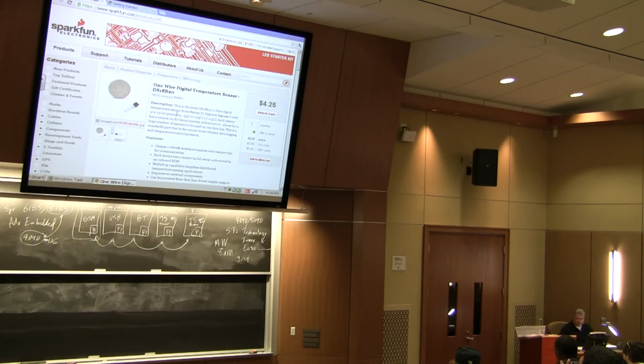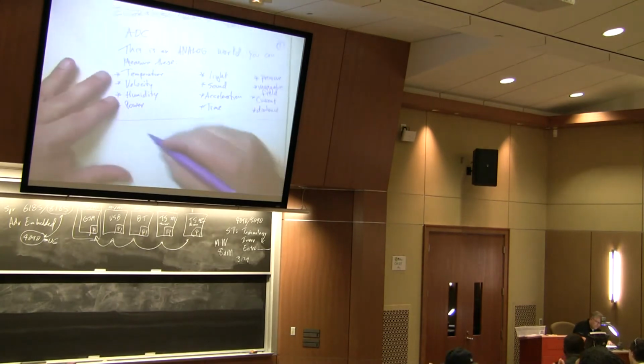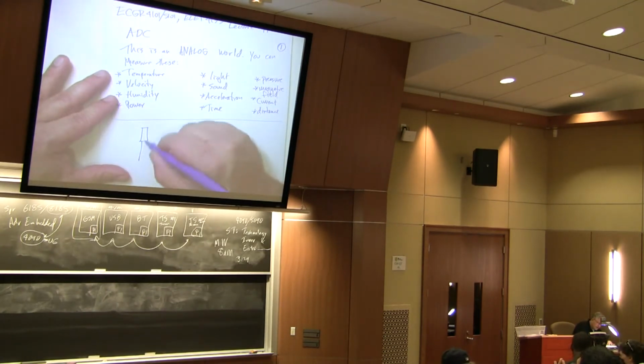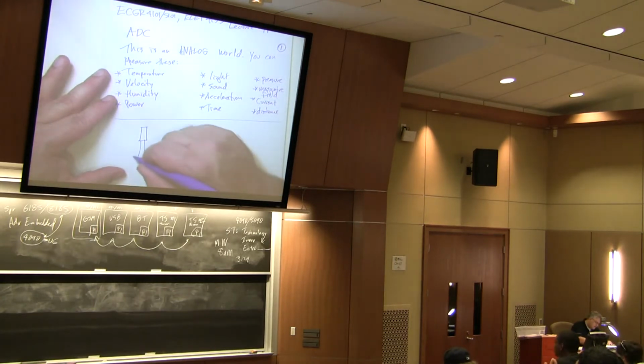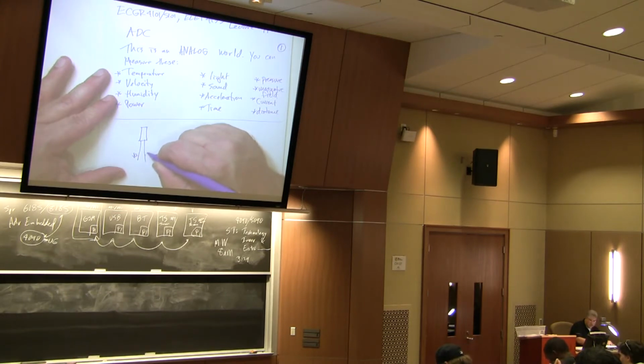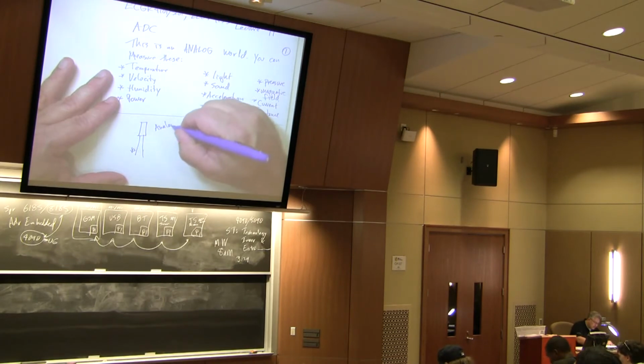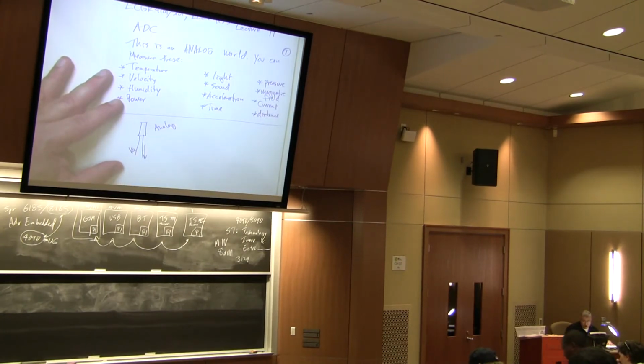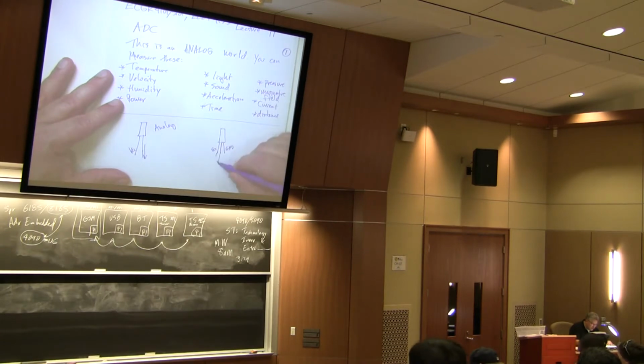We have an interesting situation with this. I can do one of two things. I could provide a device here that uses analog. So in other words, you give it a voltage, VCC, and then you measure whatever is on this leg. Or, with this other part I just identified, I give it VCC, I give it ground, and on this single wire right here, it's going to provide me with a serial communications signal.